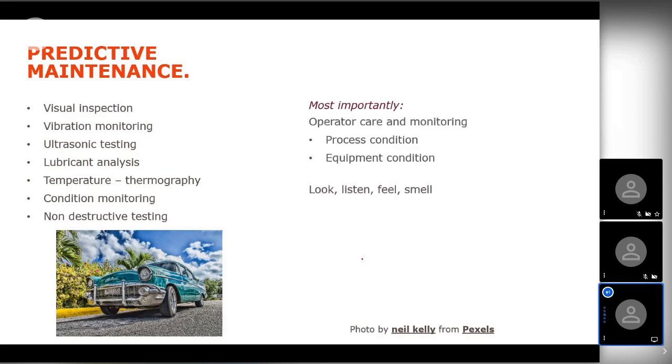But don't forget operators. The operators are there every day. They know how the equipment runs, sounds, behaves. Get them to look at it, listen to it, report any defects. It's a really good way of monitoring the condition to detect a lot of the defects that we could possibly have.